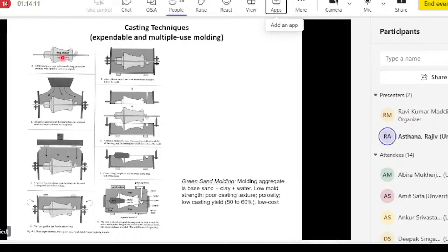Most often we use a match plate, which is basically a metal plate or a wooden plate pattern, with the risering and gating system already mounted. You put the match plate between the cope and drag, put sand, clay and water mixture on one side. The whole thing is vibrated, and then you can use a squeeze and jolt machine. And then this compressor or platen will press down the sand.